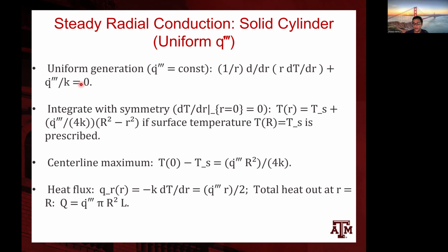And also for the heat flux, there is some radial dependence because of the fission products and the plutonium and the self-shielding, which is related to the neutronics of the problem. However, we can ignore that for simplicity and take average values of the heat generation and the thermal conductivity.